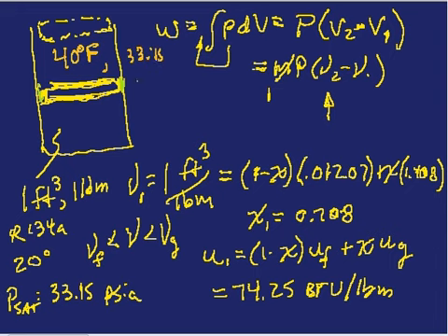So go to another page and we find that at state 2 we have to interpolate to find the volume. We interpolate between 30 and 40 psi in the table. So to do this, between there I'm at 33.15, so that's a fractional distance of 0.315 between those 2 points.